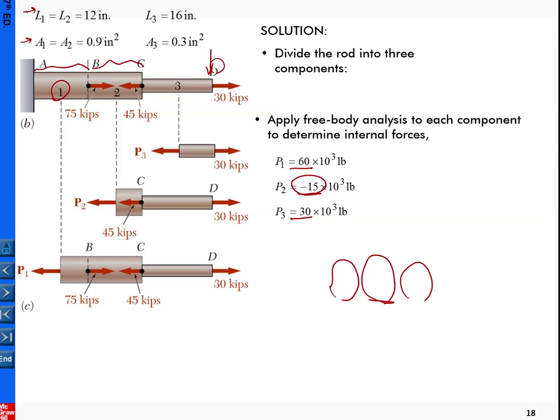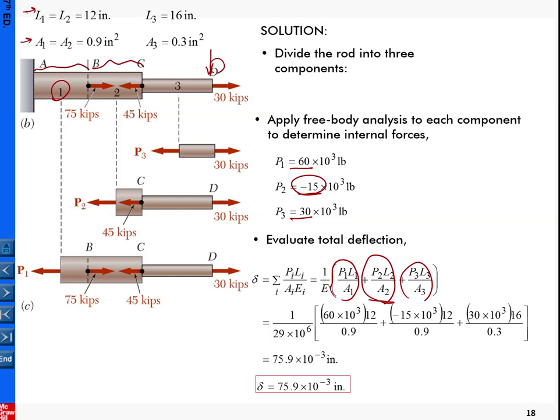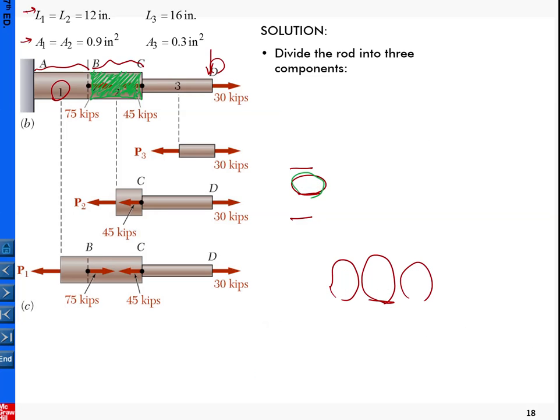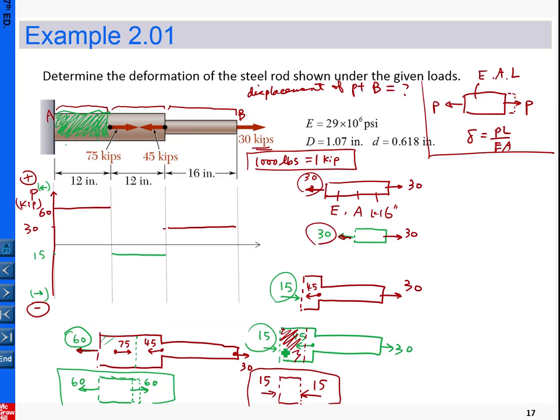So that is the reason we put a positive sign in the calculation here. And similarly for the second portion, all the material in the second portion, if you are not picky, let me not include the boundary, just inside here, all the material points in this segment are under compression, because again from the previous slides everything here is compressive.